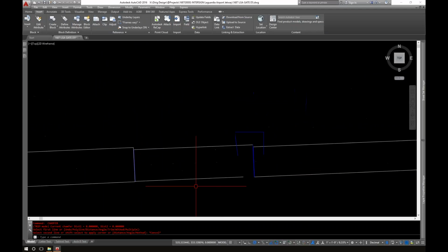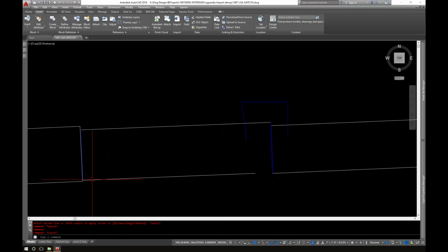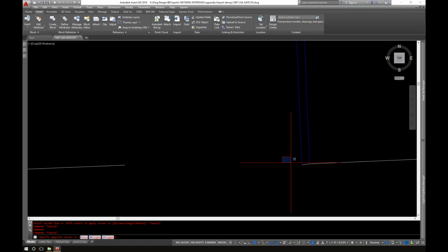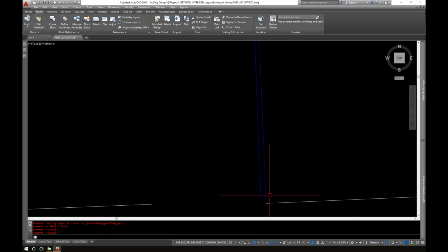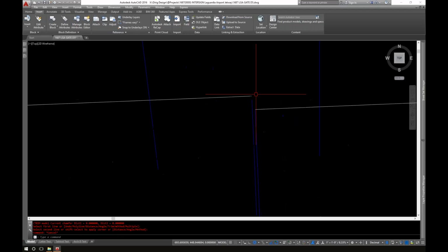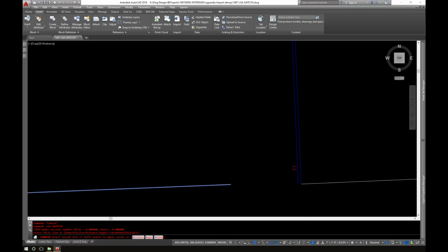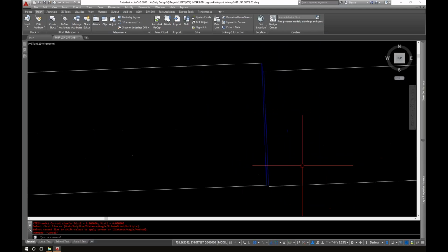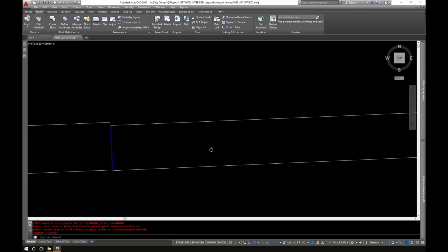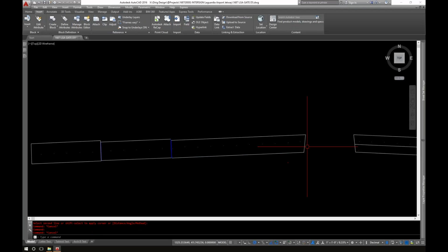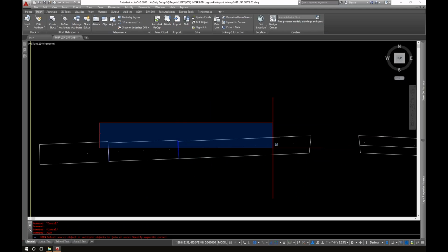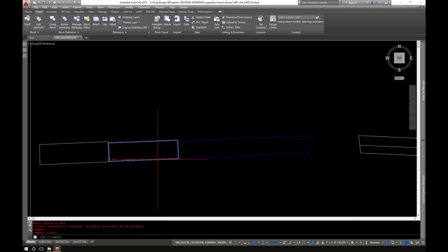Now I'm curious why that is the way it is. Because really that doesn't matter. This is going to be chamfered. This is also chamfered. This can be deleted. I'm going to chamfer this from here to there. Now I'm not sure why it's coming in as a step, but I think that would be fine. Now same idea here. We got one bottom line. So now I'm going to just join basically everything that's left. So now that should be continuous, and then down here it says closed.